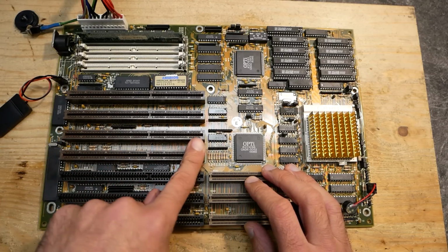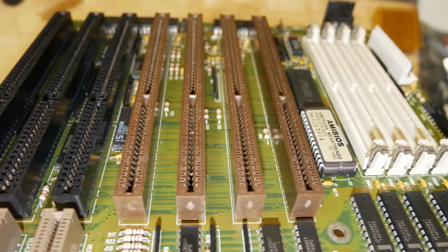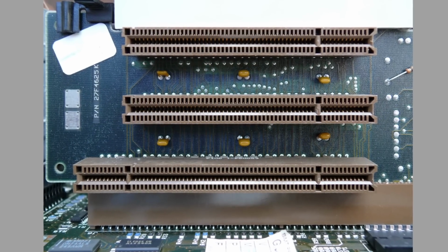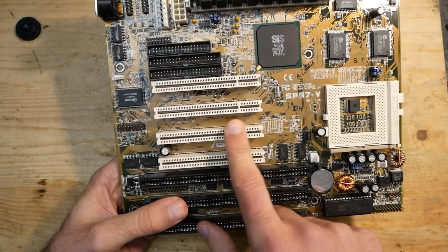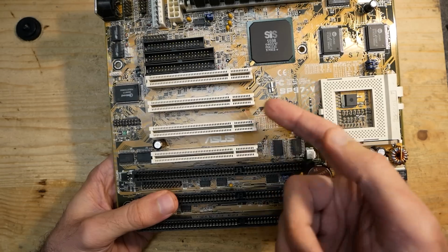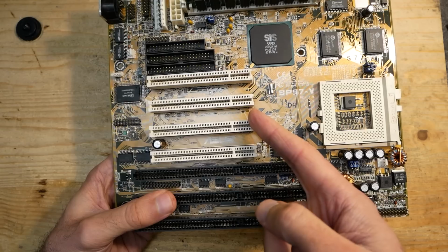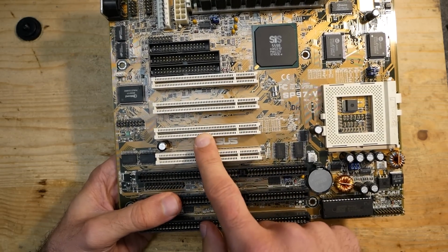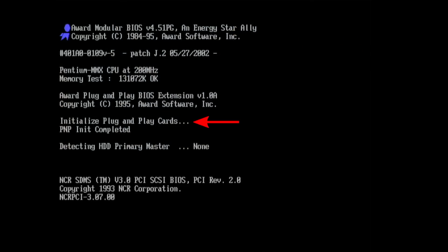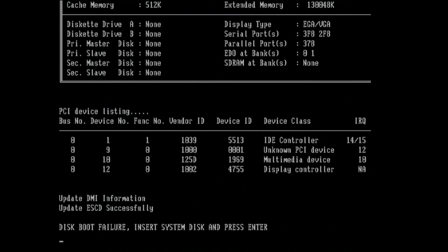Well, and the last question for today is, what happens to EISA later? Both buses, EISA just as IBM's MCA, came to their end with the introduction of PCI, which was a 33 MHz 32-bit bus, comparable from the performance point of view with VLB, but with most of the benefits of EISA and MCA. Not only was it a fast and stable standard, it also integrated that software-driven configuration which we all know today as plug and play. It was not quite as versatile as the EISA configurations which I showed in this video, but it took over the automatic resources configuration of IRQ and DMA.